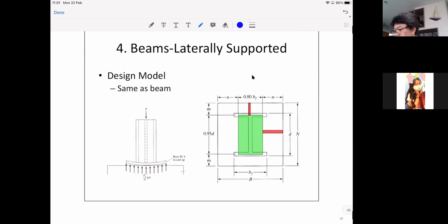So when you have the plate, the concern is what would be your n for the calculation of the moment, okay? Because as before, Fp is the stress Fp, right? Fp is equal to P divided by Bn. So when you know the pressure here, what would be the n?